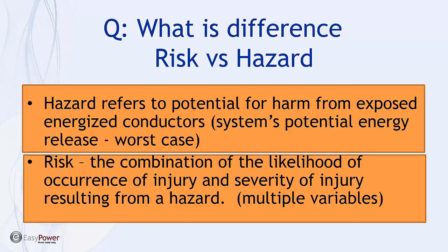So there are multiple variables, and NFPA 70E has an extended decision tree and metric system for assigning weighted levels to the different risks involved, but places the burden upon the facility owner to incorporate that in the decisions that are made about the system's safety condition.